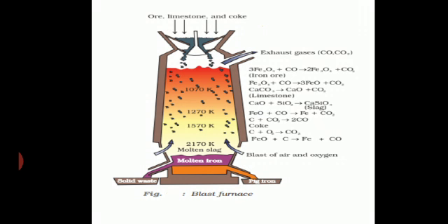At the bottom of the hearth it is being collected. Any iron oxide left unreduced so far also gets reduced by coke in this zone, and any impurities of silica or alumina still left combine with lime and form fusible slag. The slag, being lighter, floats over the molten iron, as I've already said, and it prevents the molten